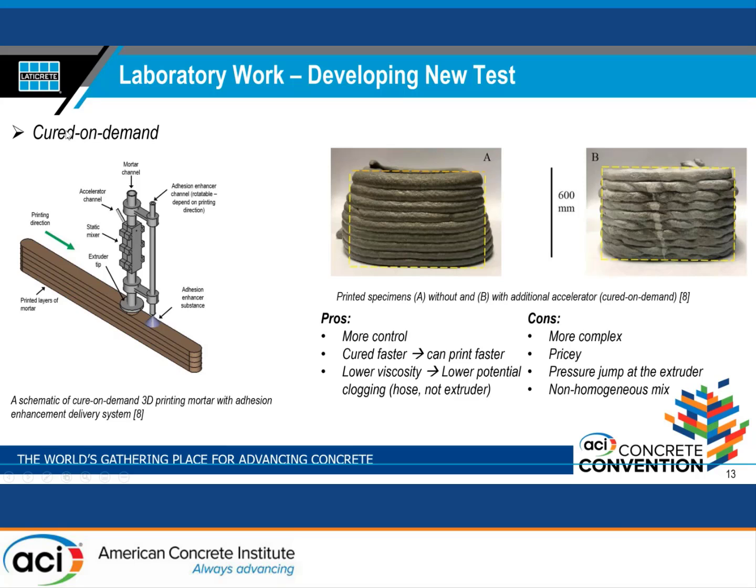However, with these technologies, obviously, it becomes more complex because of the need to control the accelerant dosage and the printing, and so on, and also it comes with a price. And having it intermixed here is not easy. Some static mixers might not be sufficient for us to have the mix be homogeneous.